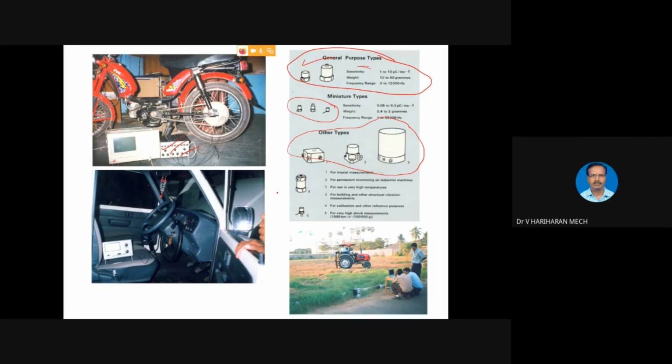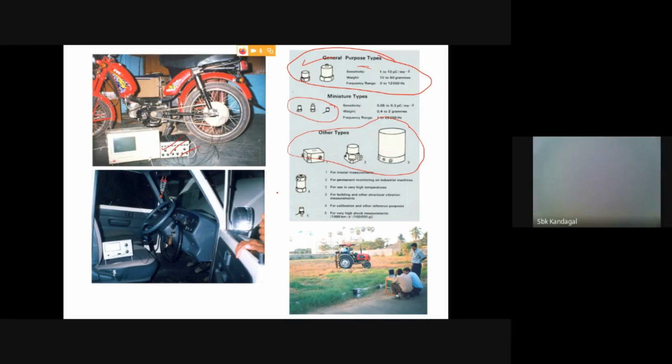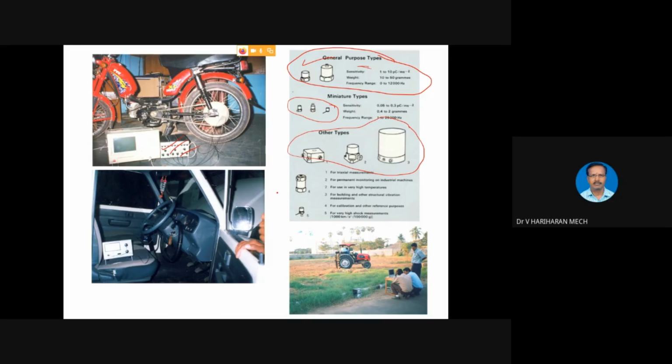Sir, is there any specific procedure for balancing turbine rotors? See, first you have to start with single plane balancing, and then subsequently go to two plane balancing, and then you have to put the cascading of the blades and do the turbine completely. There is a systematic procedure, and one has to follow that.